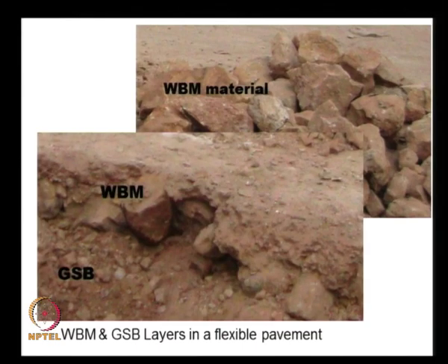And here we see some examples of these base course materials. This is the WBM, waterbound macadam. These are actually very large size stones, and here you see the cross section of a flexible pavement with very large size stones that are bound together by using some gravelly soil, muram soil, and below this we see this GSB, that is the granular subbase, and both this WBM and the GSB layers are usually highly porous, so that they also act as drainage layers in our pavements.